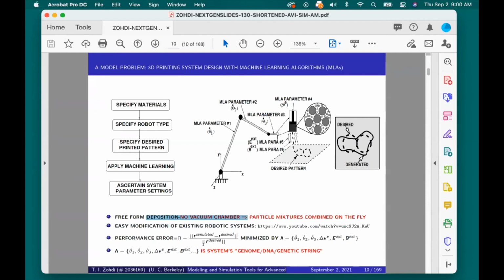them onto the surface. So the performance metric here in this case is going to be what the robot did, shown here in solid, and what we want the robot to do, which is the figure 8. We take the L2 norm and the difference between the dashed and the solid. We give the robot a score based upon what the parameter settings were. We say good robot or bad robot. Good robot has a low error. Bad robot has high error.